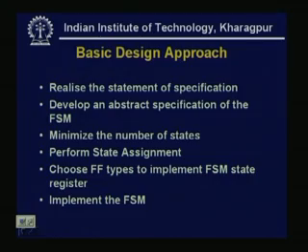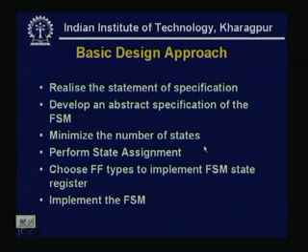Then minimize the number of states, because always our aim is to design a compact machine or compact circuit or minimized circuit. So, if n number of states are needed, then at least we need log n number of flip flops.